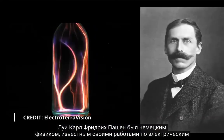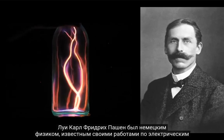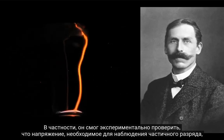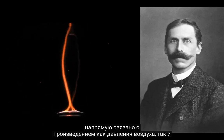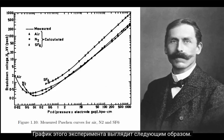Louis Carl Friedrich Paschen was a German physicist known for his work on electric discharges. In particular, he was able to verify experimentally that the voltage required for a partial discharge to be observed was directly related to the product of both the air pressure and the distance of the air gap. The graph from this experiment looks as follows.